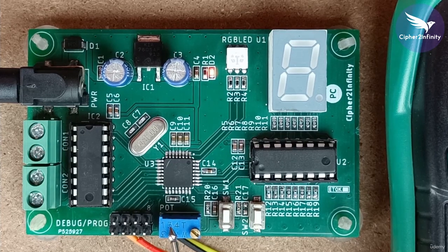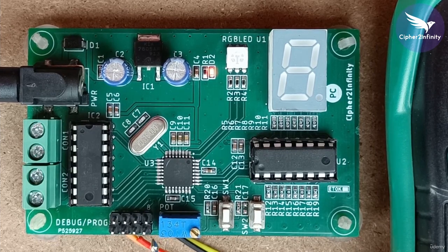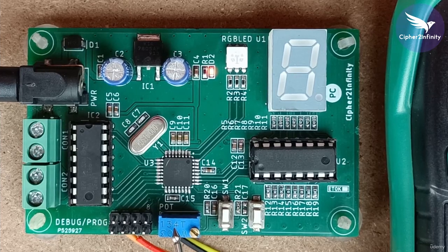And after that, the mistake that you should avoid when you deal with the preset is this: before soldering the preset on the PCB, you have to externally check whether the preset is working properly or not. I mean, you have to check with the help of a multimeter whether the resistance of the preset is varying or not.